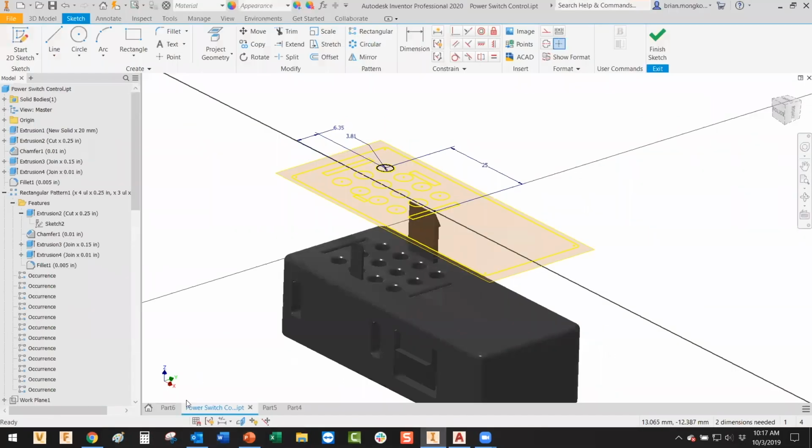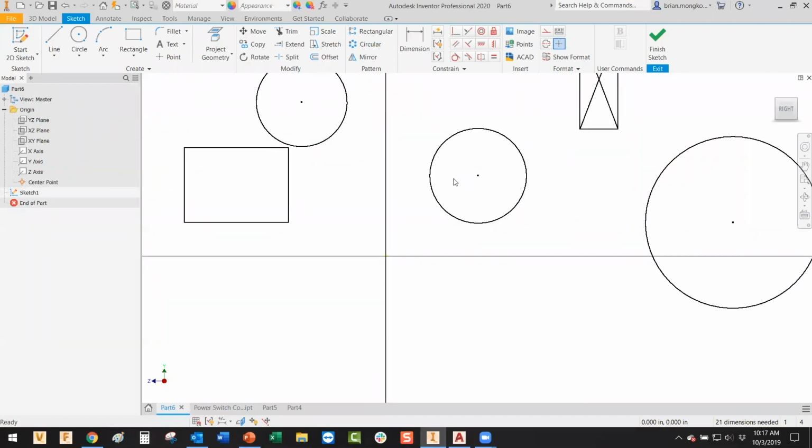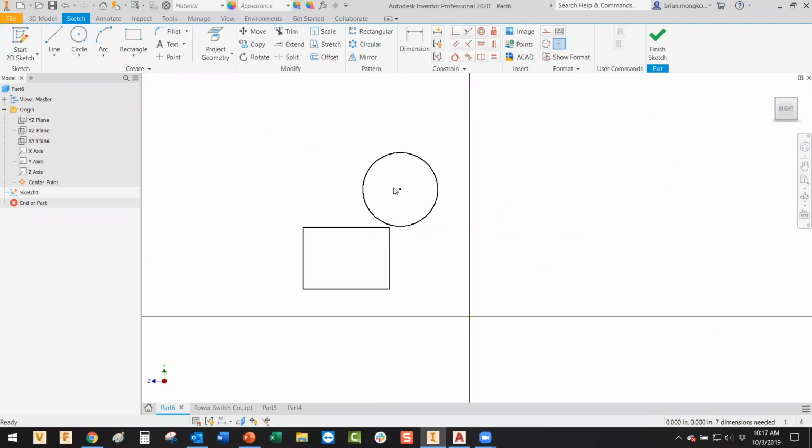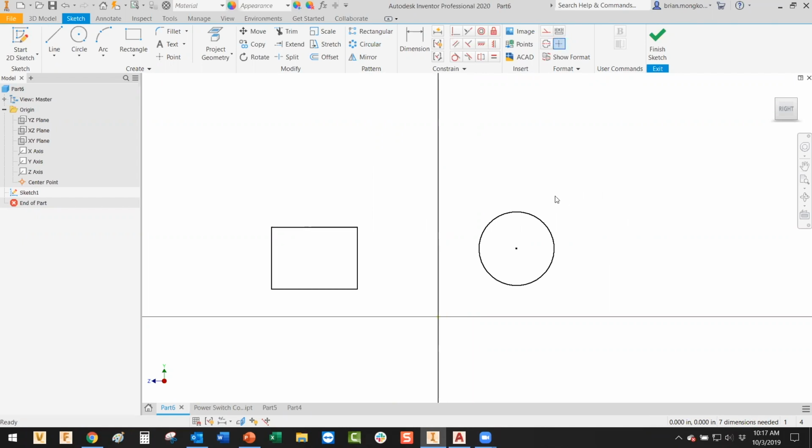So for example, if we go to a drawing here, and we have these two models here, you can see that the circle is free to move around. It's not really defined at all. But if I start adding dimensions here, let me show my center point there. If I dimension the center point from the origin here, I tell it I want it 5 inches from the center. Now I've partially defined this center point of the circle, and it could only move up and down